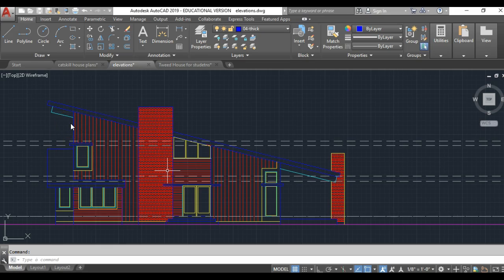Again, those two planes are meant to play off of each other as similar, so I've left them the same line weight. So again, in summary, things you cut through are thickest. Things that are deeper in the plane, the things that get further away from that cut line, get thinner and thinner line weights. But also, if you have a surface or a set of surfaces, the edges are darker than the more internal elements of that.